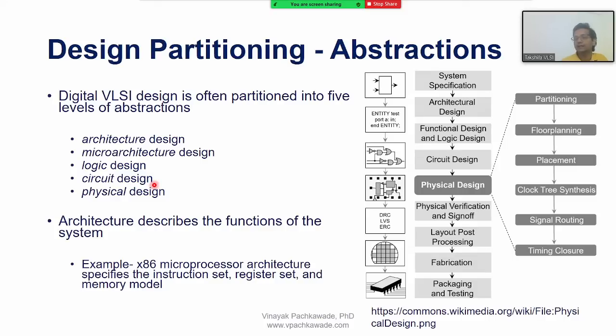Memory can be inside or outside the microprocessor. So how will those logics be implemented with circuits, because we know that we use transistors to implement those logics. And finally, once the circuit design for each block has taken place, the physical design team's job is to understand each of those blocks, how the layout will be performed, how they will be placed, that is floor planning, and how they will be connected to each other, that is interconnection, or signal routing.